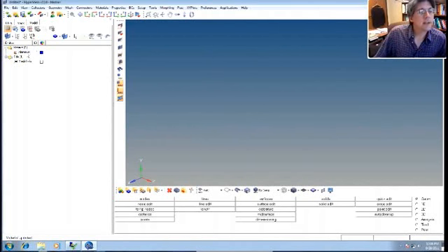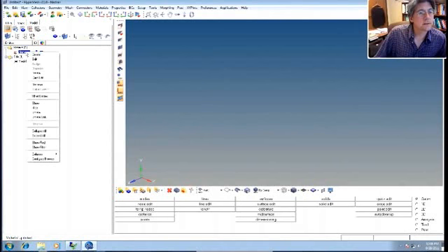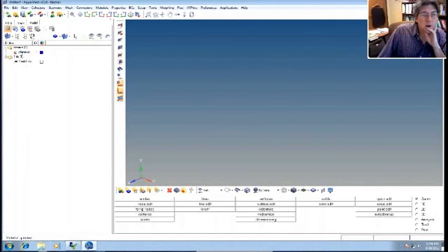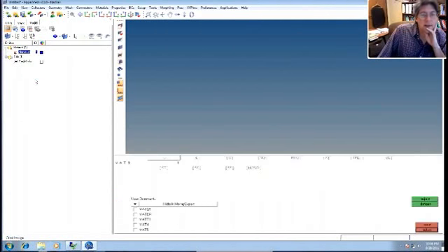Okay. Now we actually have to go in and put in the properties. So there's edit, but when we want to actually edit the card inputs like you would in Nastran, these are the different fields, you want to use the card edit. So when I right click on aluminum and hit card edit, what pops up is a little spreadsheet that looks just like the input in the Nastran reference manual. These are the fields that you would actually type in your DAT or BDF file. Here's the ID that you can't edit; it automatically assigns that. Young's modulus, Poisson's ratio, density, and so forth.